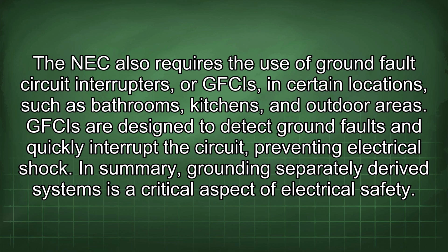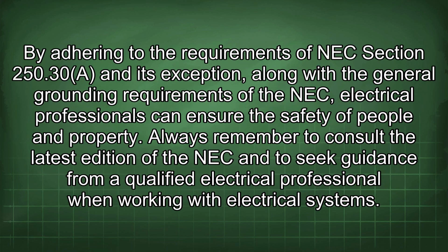The NEC also requires the use of ground fault circuit interrupters, or GFCIs, in certain locations, such as bathrooms, kitchens, and outdoor areas. GFCIs are designed to detect ground faults and quickly interrupt the circuit, preventing electrical shock. In summary, grounding separately derived systems is a critical aspect of electrical safety. By adhering to the requirements of NEC Section 250.30 and its exception, along with the general grounding requirements of the NEC, electrical professionals can ensure the safety of people and property.